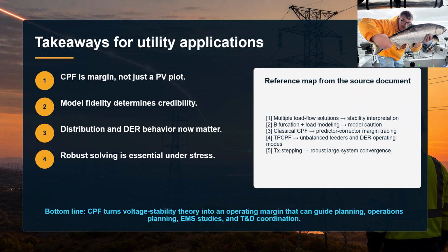So some key takeaways. The main one is that CPF is margin, not just a PV plot. Second, model fidelity determines whether the margin is credible. Third, distribution and DER behavior now matter because they can affect both local feeder voltage and bulk system reactive needs.